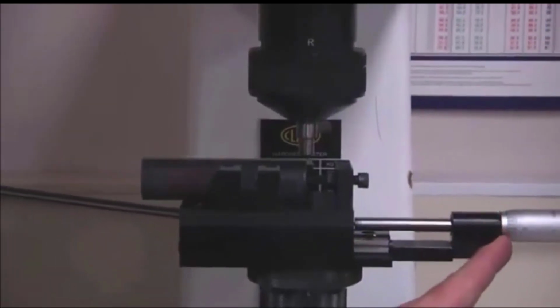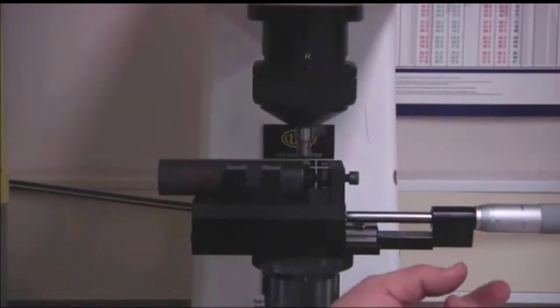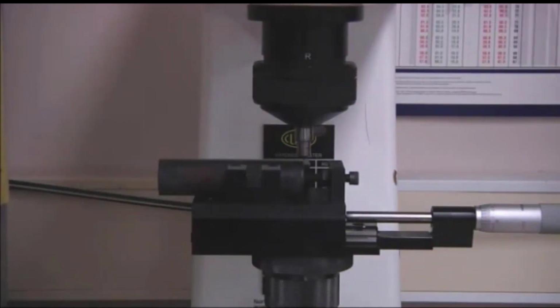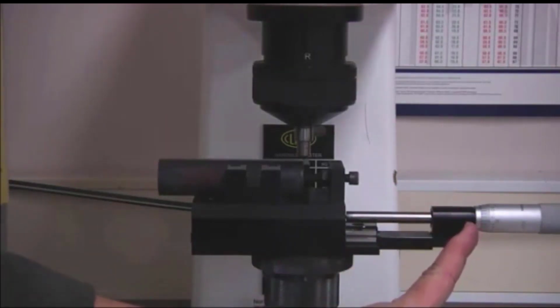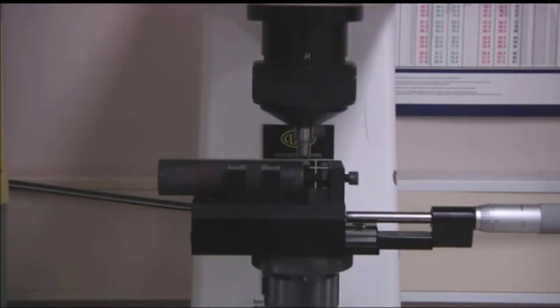So right now it is set for 0, and it's marked in increments of 1/1000th of an inch, and it's 25 thousandths of an inch per complete revolution. So for ease of convenience during our experiment, I've had another minor deviation from the ASTM standard. We're not measuring at the exact locations prescribed by the ASTM standard. They're very slightly off, and I've just modified them so that they are increments of 25 thousandths of an inch. So it's 1 whole revolution or 2 whole revolutions distance between our measurement points.